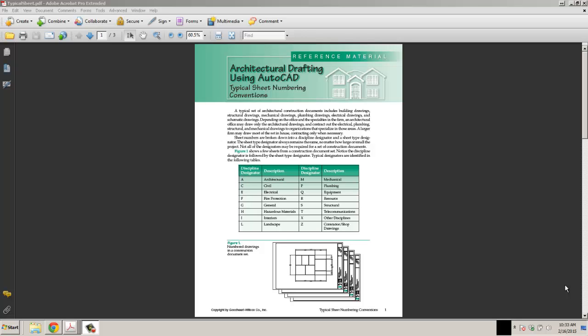If you look at that page 19 and kind of thumb ahead to page 663, they show a series of drawings, and there's a specific order that drawings need to go in. Normally we start out with a cover sheet that describes the drawing of the project. There may be an architectural rendering on it. Sometimes they'll put their index.